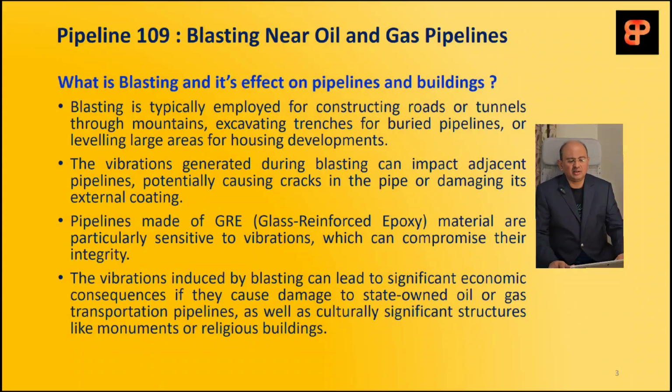So let's see what is blasting and its effect on pipelines and buildings. Blasting is typically employed for constructing the roads or tunnels through mountains, or excavating the trenches for buried pipelines, or leveling large areas for housing developments. The vibrations generated during blasting can impact adjacent pipelines, potentially causing the cracks in the pipe or damaging the external coating. If the pipelines are made of GRE, which is glass reinforced epoxy, which is a bit more sensitive material to the vibrations, then it can compromise the integrity of such pipelines.